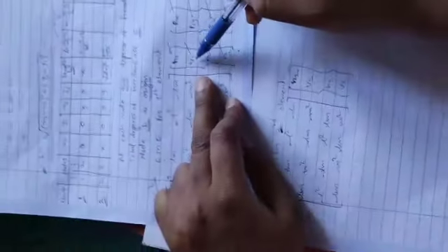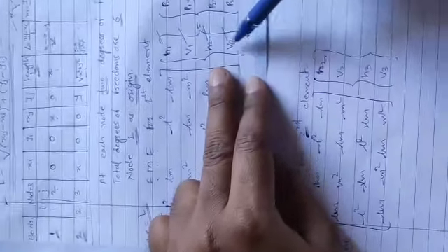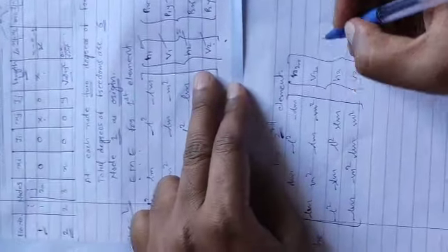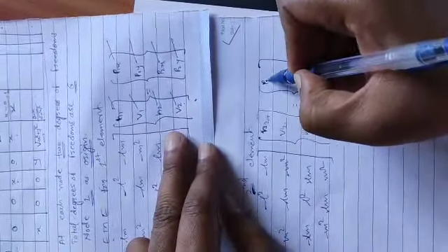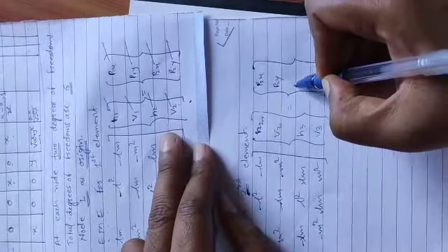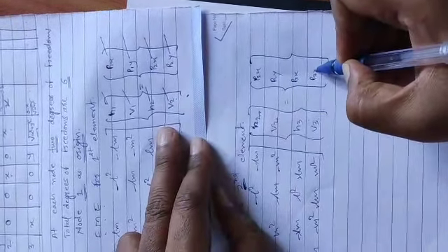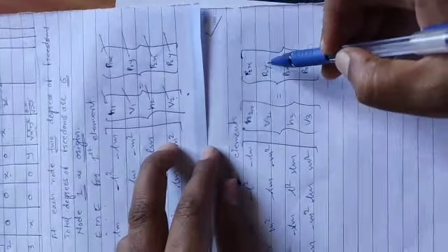As we have seen before in the first element matrix equation, horizontal and vertical displacement at node 1, similarly at node 2. And forces P2x, P2y, P3x, P3y. Here horizontal force and vertical force at node 2, or the forces along x and y direction at node 3, all are shown.